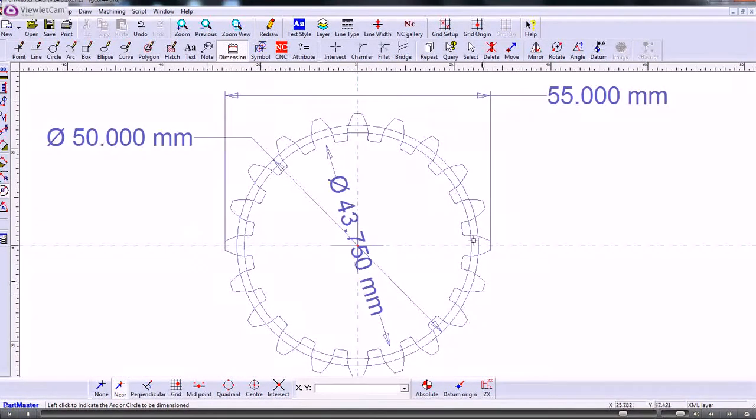For instance, you might need to remove some of these teeth if you were doing a particular type of cog design. So that's how you use Involute. Start off with the CAD, call up the Involute function, produce an XML file and import it back into the CAD, or you can use the Involute as a standalone module and export to DXF to some other software. Okay, that's it.